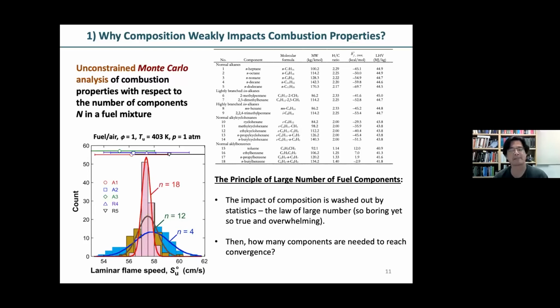That is the reason we can start to decouple the process of fuel pyrolysis from subsequent oxidation of pyrolytic product by molecular oxygen. Those are the physics indicated by the measurement: fuel pyrolysis first, fragment oxidation next, and fuel pyrolysis is not affected by oxygen concentration.